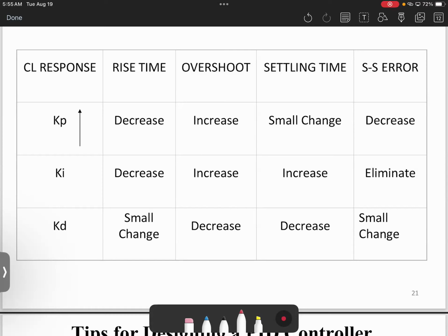However, with PI alone there will be oscillation. With a poor design, going to floor 100, it will go to 102, back to 92.8, then to 101, then back to 99. An elevator that goes up and down would be annoying. When you use a PID, it removes the whole problem.